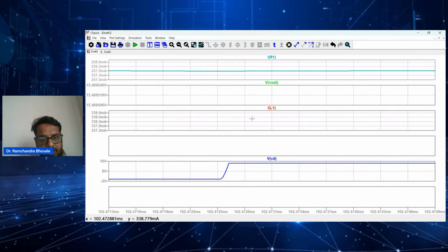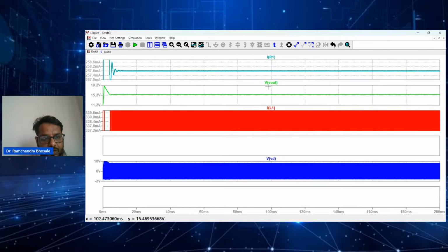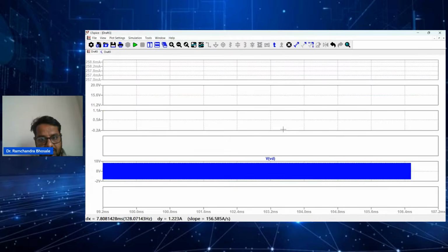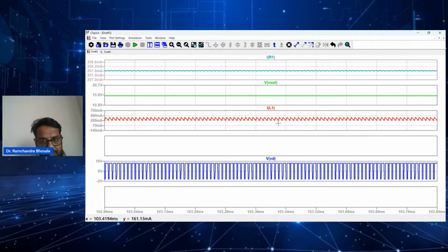And now I will do it for input. So input current is IL1. Fit. Okay, so IL1 average current I'll take. If I just press control and click IL1, I'll get the average current as 350 milliampere. So 350 milliampere into input voltage of 12 volt, so divided by 12 times 0.35. So I'm getting 95% as the efficiency. Okay, so this converter is 95% efficient.